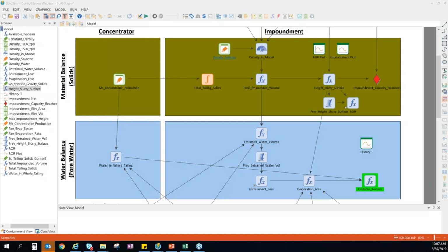There have been operations completed where we will actually sample the tailing. There's special barges that are available that you can actually get out onto the impoundment. And sometimes, depending on the level of consolidation and rate of deposition, you might even just be able to develop a roadway out onto that impoundment. Again, I would think that's a pretty unique case, but I've seen it done. Then from there, you can sample by SPT, you can sample by grab samples, you could really do what you need to do to get those samples. But ultimately, the short answer from my limited experience in this area is that sampling is a preferred option.